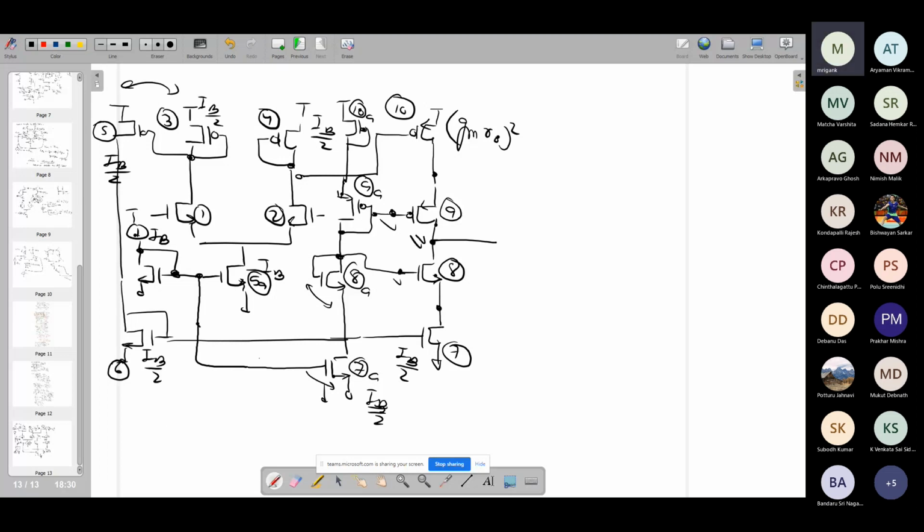There are other ways also in which you can probably improve the swing, right? So the allowed swing, etc., you can improve. That requires, say, whatever current mirror topology we have discussed earlier, right? Reduced swing Cascode. The same topology can be applied here as well.